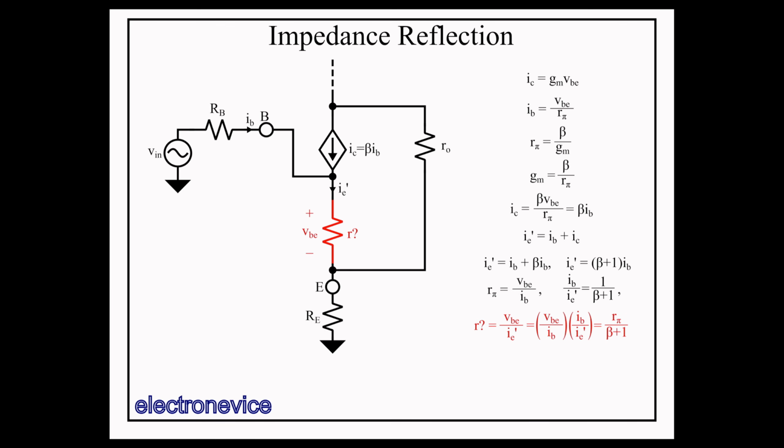With R pi, we can simplify the resistance even further by unpacking R pi and simplifying to get alpha over gm, which we define as the small signal resistance little re. This circuit is actually a different model from the hybrid pi model, called the T model, which is sometimes easier to use to analyze some circuits, but is mathematically equivalent to our hybrid pi model.